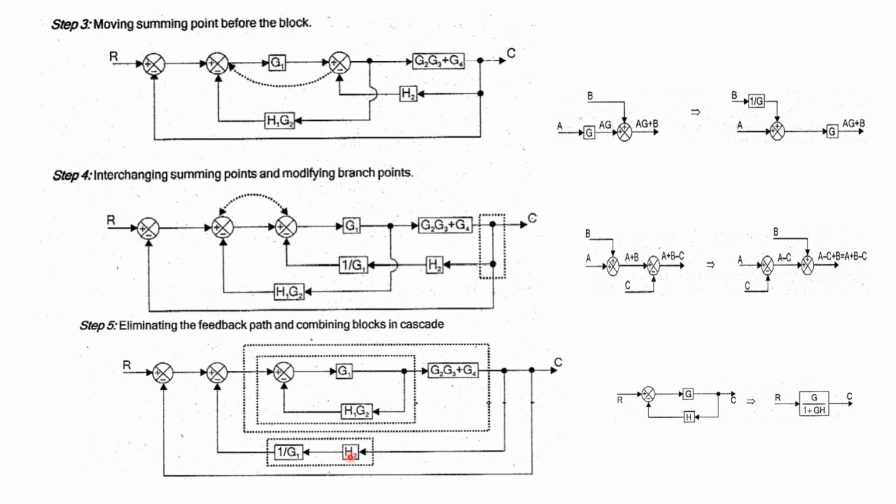Understood? Now from the single branch point, the signal is going to this loop and also this loop. These are all the same points, isn't it? So from this point, we can give the signal to this loop, and also to this summer here. Now this will be the diagram. This will be a negative feedback, and now we can apply the formula for negative feedback.